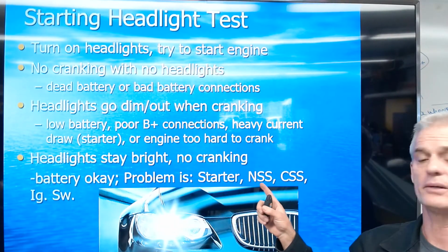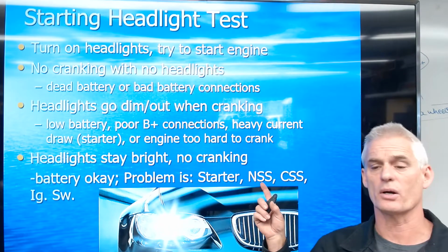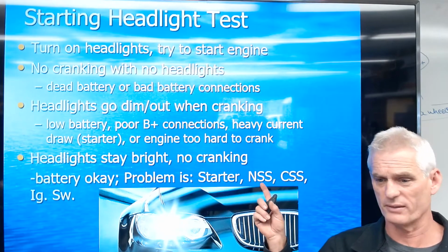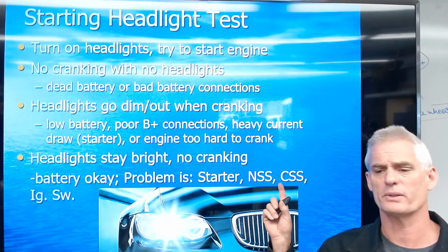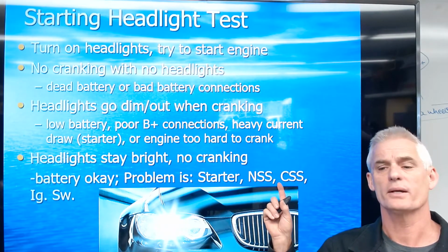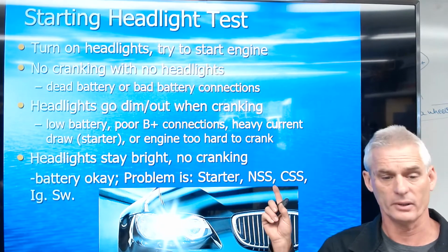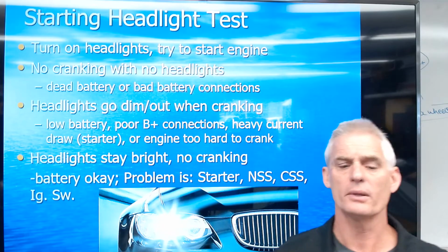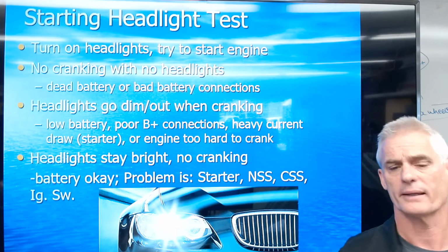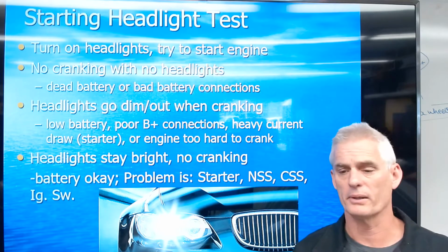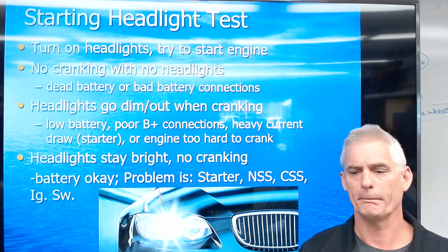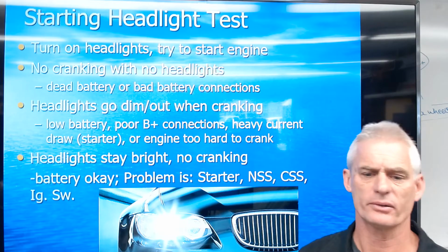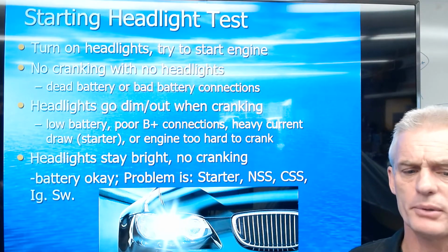It could be with that neutral safety switch that doesn't let you start unless the car's in park or neutral for safety, or a clutch safety switch that doesn't let the car start unless the clutch pedal is depressed fully so you don't start in gear. Or it could be an ignition system fault. Or what about an alarm? It could be an alarm's tripped, or a key issue where the chip is not talking to the transceiver and communicating with the computer, or it could be a computer issue.